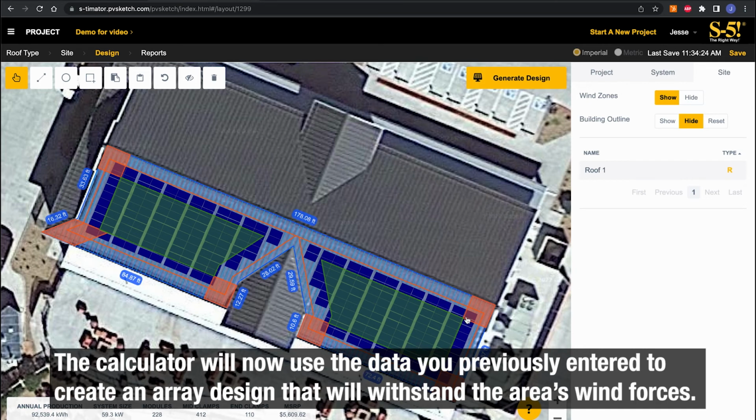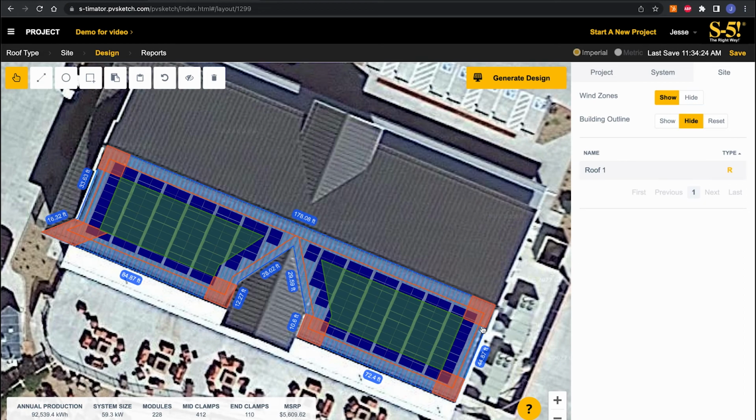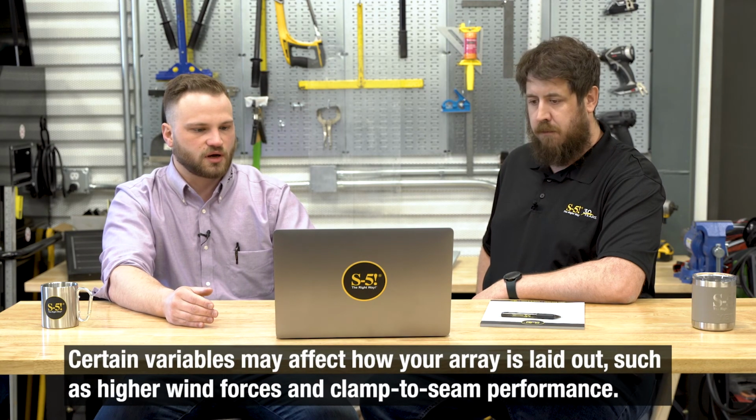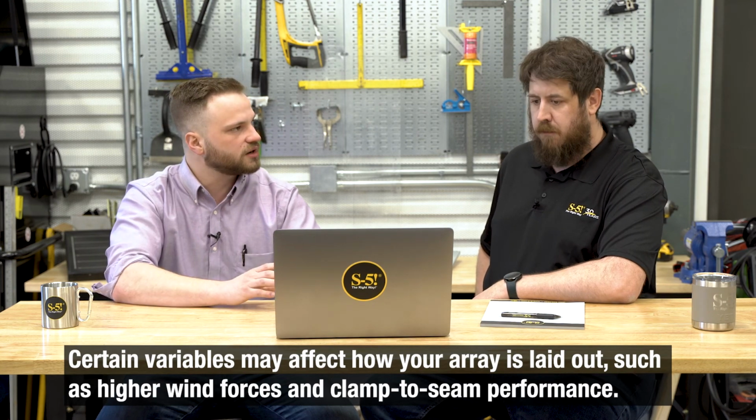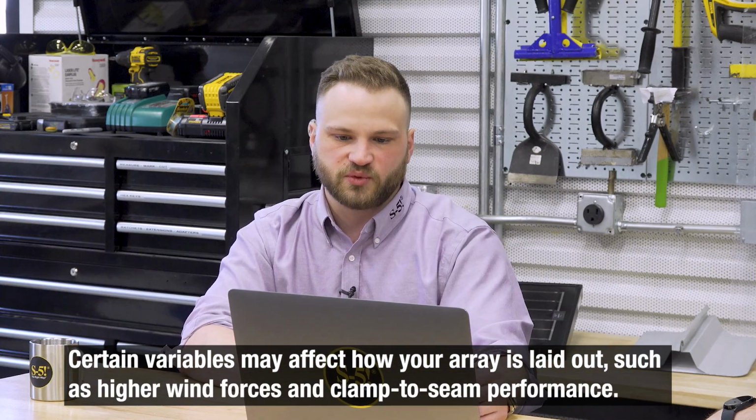You'll see in this case, the calculator wasn't too shy about putting modules at least partially into wind zone 3. There could be cases where your wind forces are higher, or maybe the clamp to seam connection is a little bit weaker, and the calculator might say we can't put modules into wind zone 3 because there's not enough seams to be able to provide enough frequency of attachment.